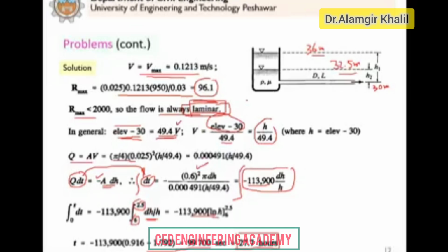Similarly, the flow can be steady flow, the flow can be unsteady flow. We can have a steady uniform flow. We can have a steady non-uniform flow. We can have a steady laminar flow, can be a steady turbulent flow. Don't try to mix things, because in laminar flow, we consider that the velocity profile is not changing in the x direction, it is a steady flow. Clear? So that's why in the beginning I told you that these are different concepts. Don't try to combine them.